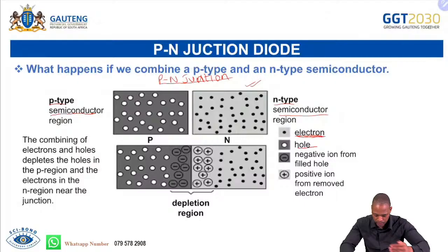They are many here because a lot of phosphorus was used to create the n-type semiconductor. I want you to think of it like that. Yes, I used only one, but that was for explanation, for understanding what is happening at the microscopic level. Now I want you to understand there are a lot of holes and a lot of extra electrons, and this is what is going to happen in a p-n junction.